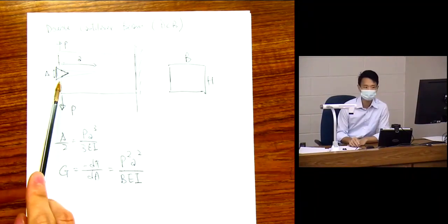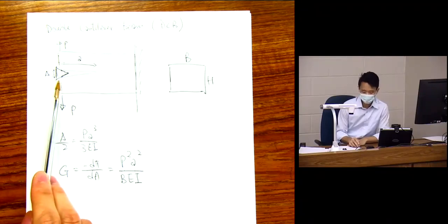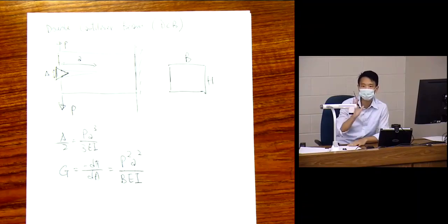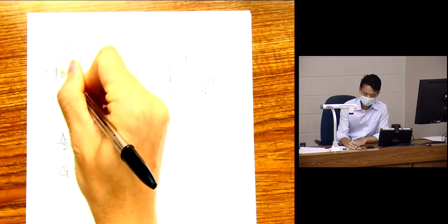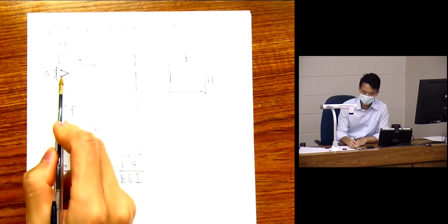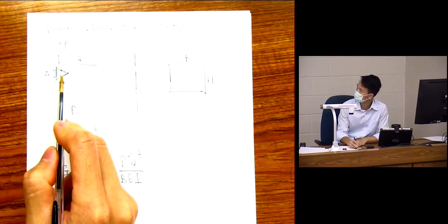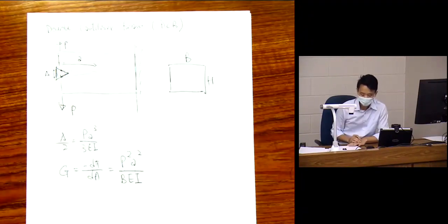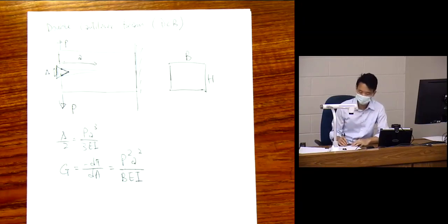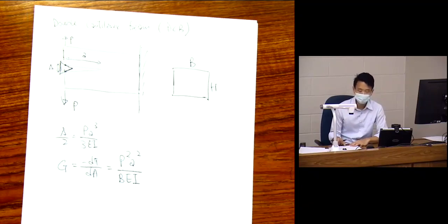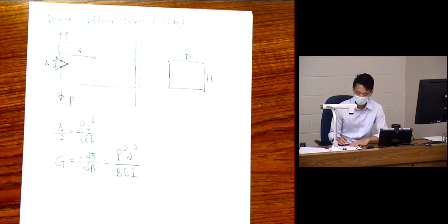However, the difference is that now I'm not controlling the force P. I'm essentially controlling delta, because I can adjust the wedge angle, and I can adjust how much I push this in. So exactly this much is delta, right? This is the wedge in this configuration, and right now this is the delta, the displacement of the crack at the mouth, right? So I am actually driving the delta instead of P, and this is a displacement control cantilever beam test.